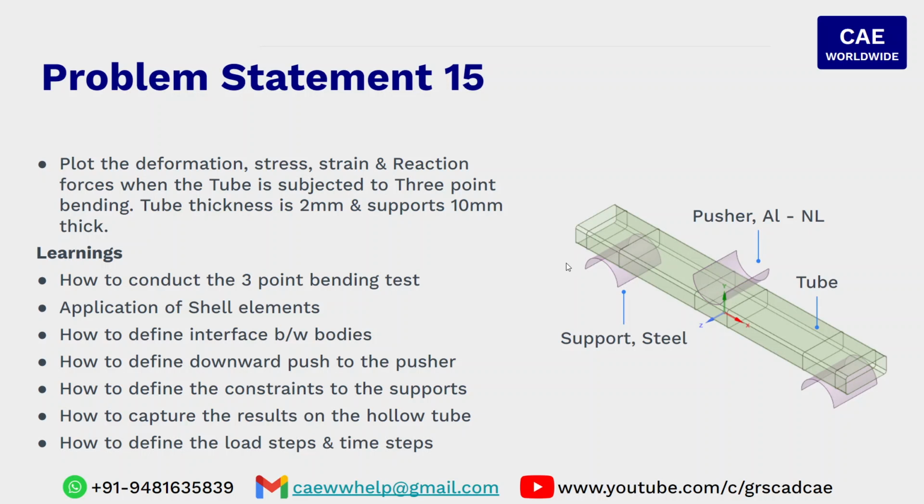The next problem is very interesting and has more demand. The problem statement reads like this: plot the deformation, stress, strain, and reaction force when the tube is subjected to 3-point bending, where the tube thickness is just 2 mm and the supports are 10 mm thick. At the bottom we can see the supports, and the top one is the pusher which pushes the tube against the supports. The center portion is a tube made up of constant wall thickness. One thing you must be wondering: all these geometries are surface bodies, not solid geometries. Yes, these surfaces are the neutral surfaces extracted from the 3D geometries to make the analysis simple and capture the behavior accurately.